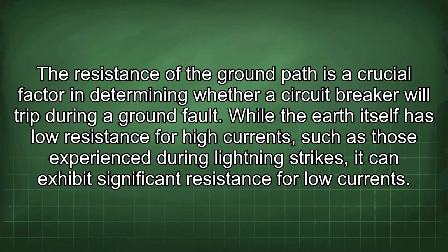The resistance of the ground path is a crucial factor in determining whether a circuit breaker will trip during a ground fault. While the earth itself has low resistance for high currents, such as those experienced during lightning strikes, it can exhibit significant resistance for low currents.